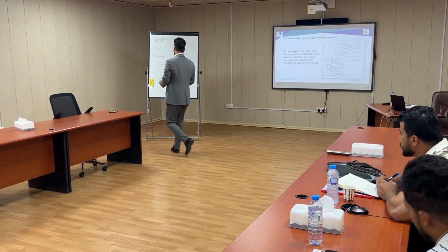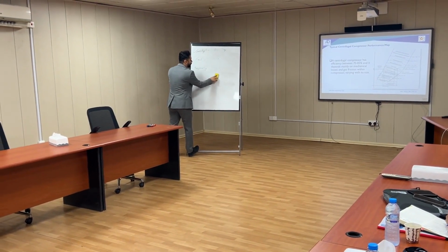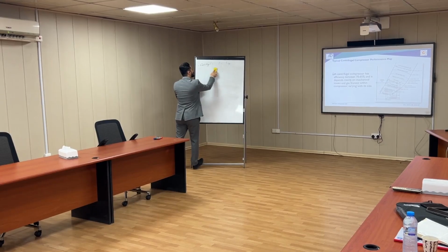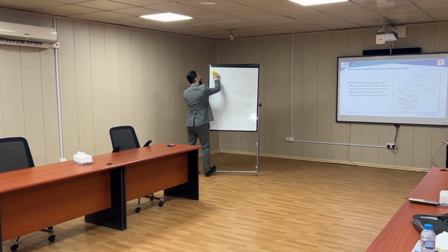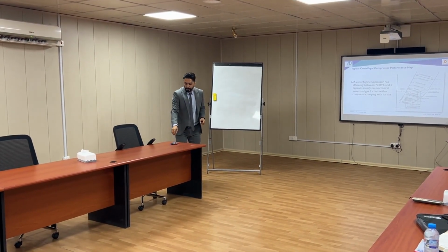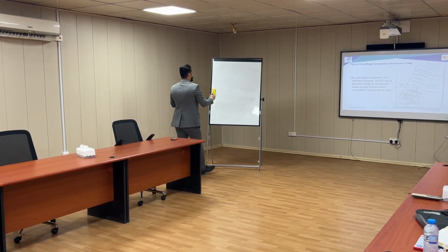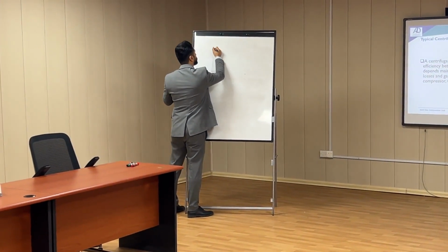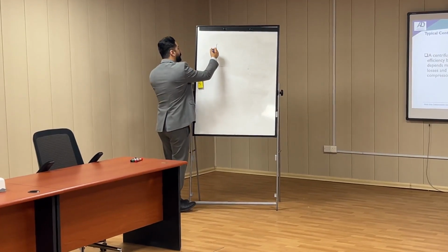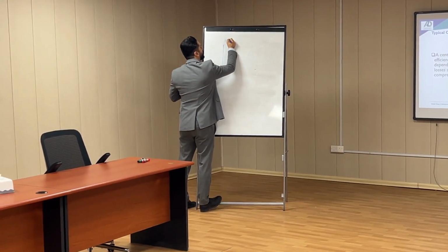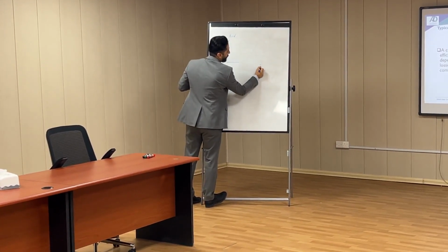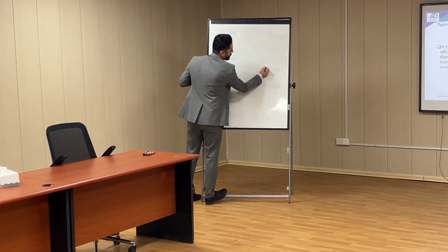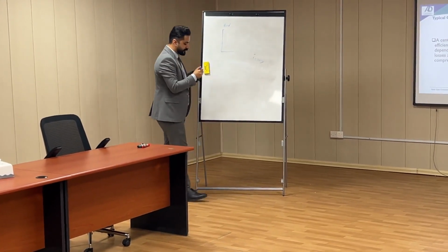And as Riza explained, we should know the flow rate of the compressor, and we should always provide a minimum flow for the compressor. Look at here. If this is the performance curve of a centrifugal compressor, we are going to know how much is the head and how much is the capacity at which the compressor is working.